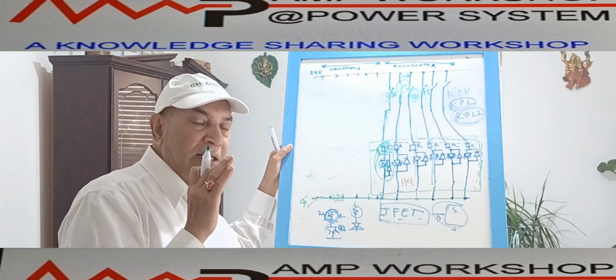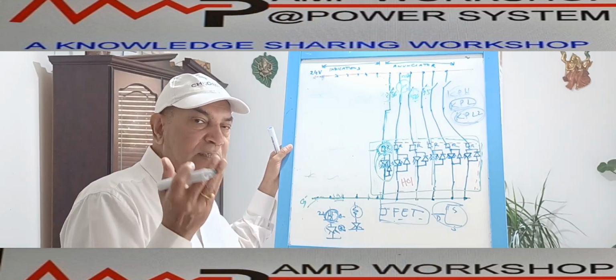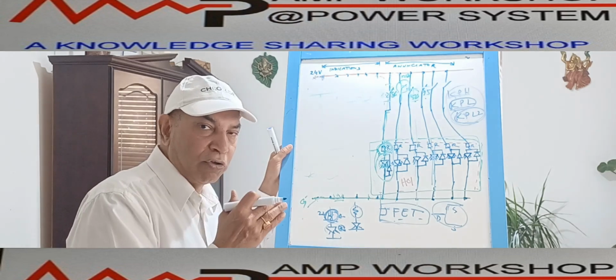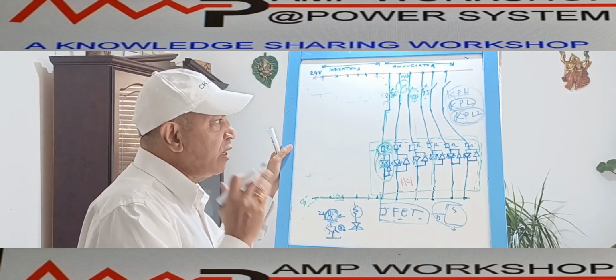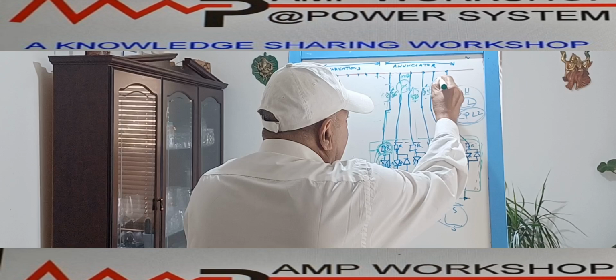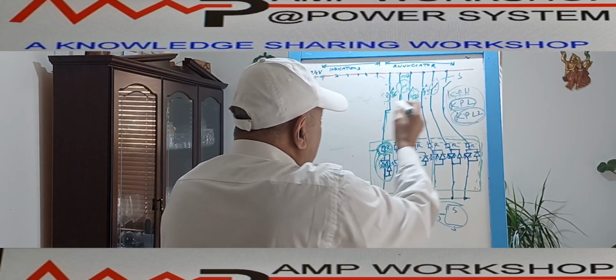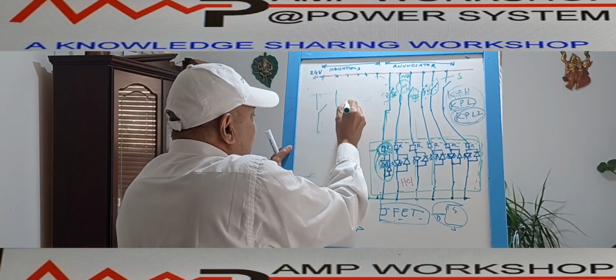So if the switchgear is unhealthy, the SF6 condition is not healthy, that needs to be monitored. How do we monitor this? We have used that control switch, we have already discussed. If we use that control switch in parallel, these are the SF6 gas pressure not healthy switches. So this is the NO contact of this. The 3 NO contacts we actually connect in parallel.